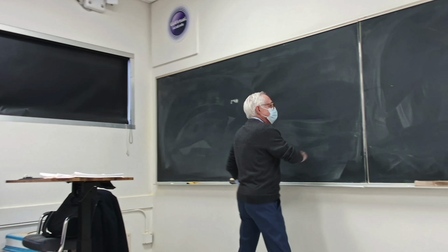The pressure decreases, of course, and the temperature decreases. So this enthalpy change is converted into shaft work. Okay. So this shaft basically rotates because of this flow through here and out. Okay, so we get shaft work, for example, in a steam turbine. We get work out of it.